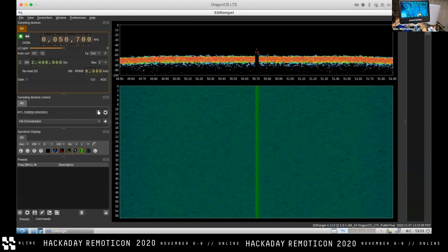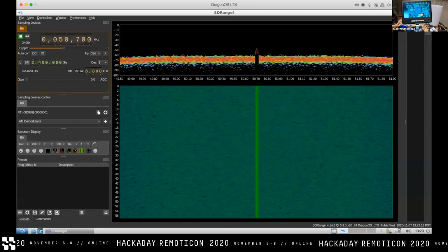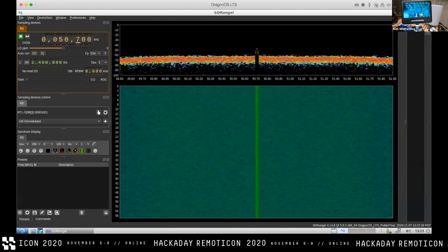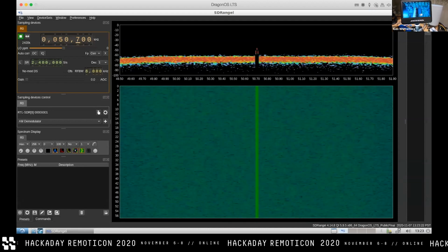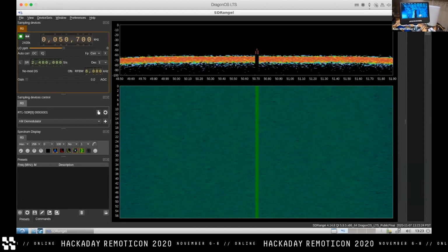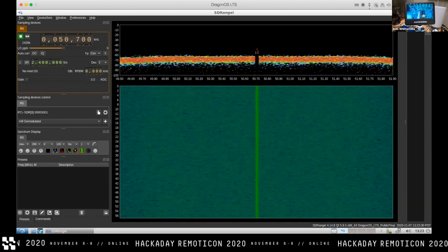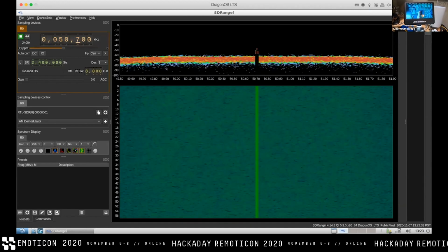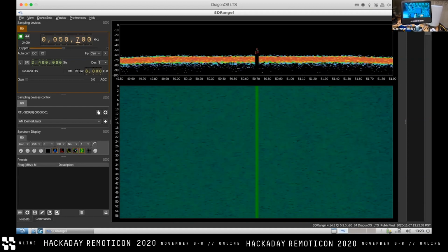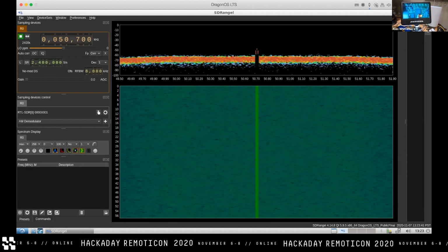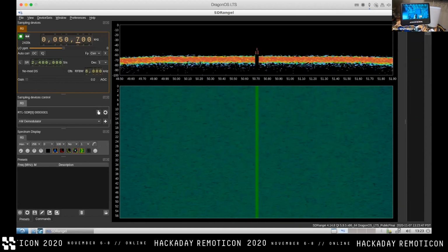Well, capacitors are definitely suspicious from a radiated noise standpoint, especially when you're looking at current through a trace. Basically what we're measuring is, with the probe right here in this orientation, we're measuring the current through that trace and into that capacitor. So what we've basically measured is that capacitor is sinking a ton of RF current at the 50 megahertz that we can detect with our loop probe. And ditto over here. So what I'm willing to bet is that these capacitors here and here are probably IO bank filter capacitors. And we're probably